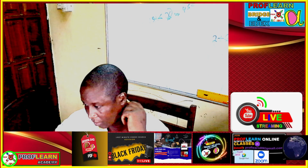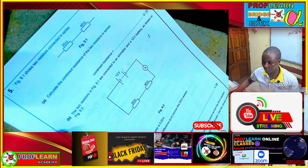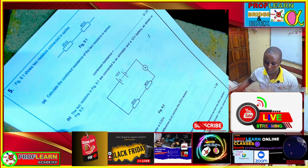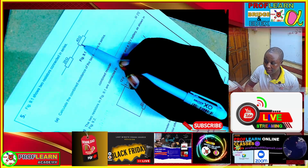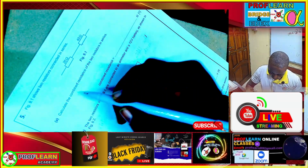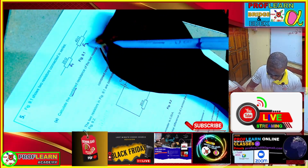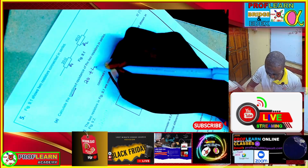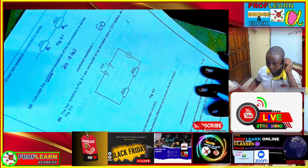If we are having this kind of resistor connection, what you need to remember is when they are connected in series, what you do, and when they are connected in parallel, what you are supposed to do. Here, these two are in series. So when they are in series, to calculate the combined resistance, you just add R1 plus R2. So this is 20 plus 40, and that translates to 60 ohms. That is the total resistance.